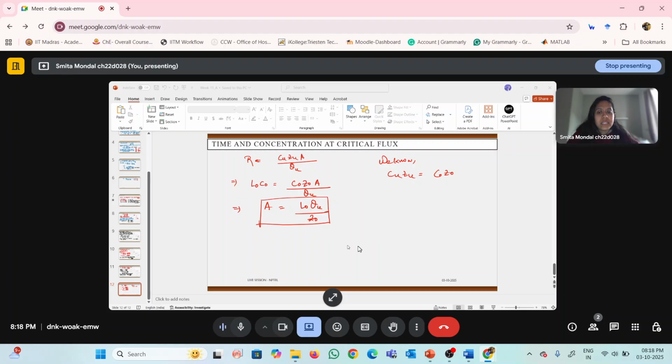These solids will not settle down completely at the bottom of the thickener. With the rising velocity, the solids will not settle completely at the bottom, and they will go up to the overflow. In the overflow, we expect clarified water, but if solids are present in the overflow, then it will contaminate our separation process. So this is what happens.